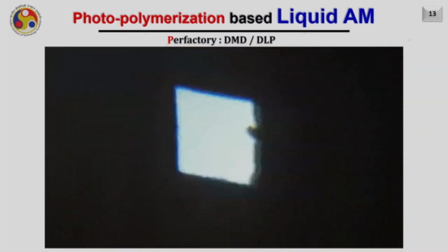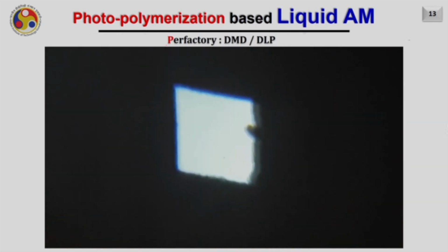The same analogy can be extended to the screen. Here you can see, if all the pixels are activated, the light will be projected completely. And if the permanent magnet moves appropriately, the particular mirror will not deflect the light. However, in a real DLP system, this permanent magnet doesn't move. What we use instead are electromagnetic coils, and each coil can be activated or deactivated through an outside source.